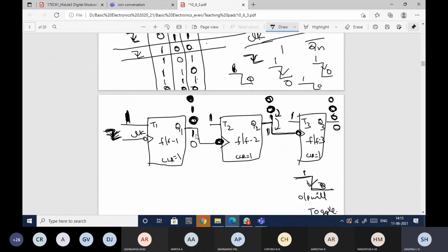0. Okay, so now observe the Q1. Q1 is changing from 1 to 0. So am I getting a trailing edge triggered clock? Yes, ma'am, for flip-flop 2. So what happens to the output? It is 1. Present state is 1. The next state is 0.